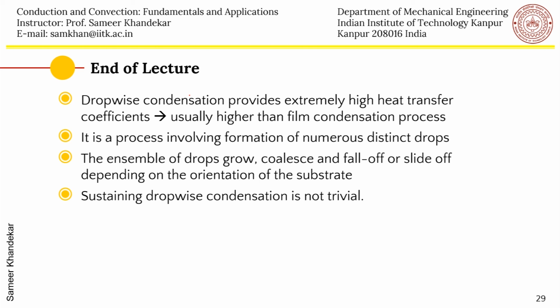Industry has been trying for quite some time to control the dropwise condensation process so that the hydrophobicity is maintained. However, after a continuous cycle of dropwise condensation, this particular film or coating breaks down or is eroded, and therefore the drops may not form, the hydrophobicity is lost, and then you can get back to film-wise condensation mode.